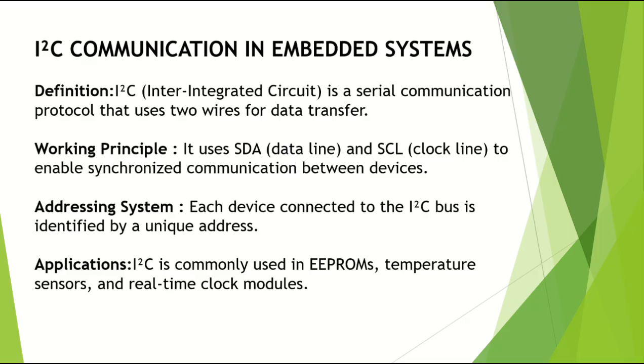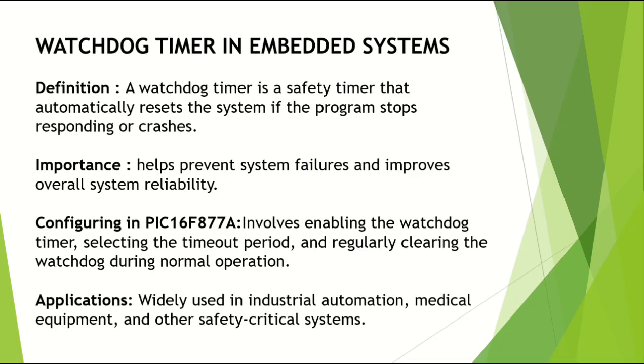Watchdog timer in embedded systems. A watchdog timer is a safety timer that automatically resets the system if the program stops responding or crashes. The importance is that it helps prevent system failures and improves overall system reliability. The application is widely used in industrial automation, medical equipment, and other safety critical systems.